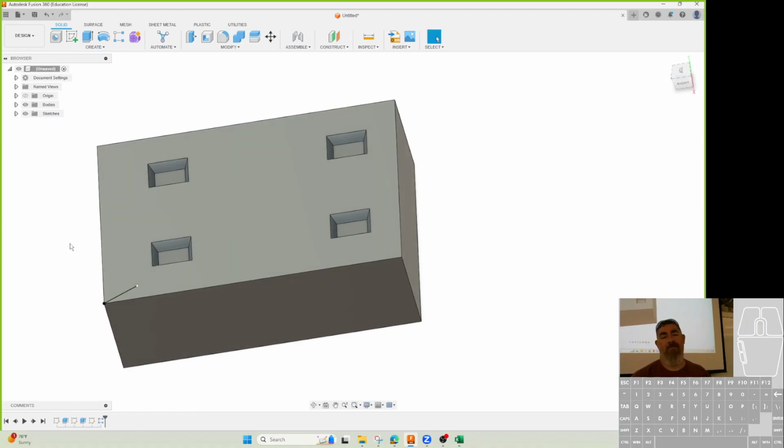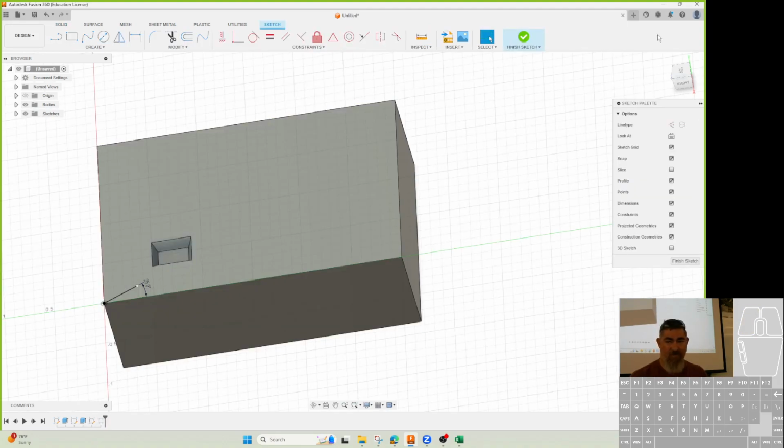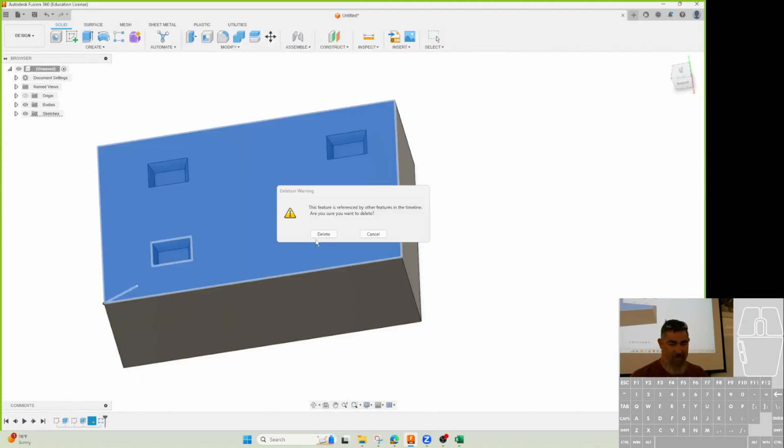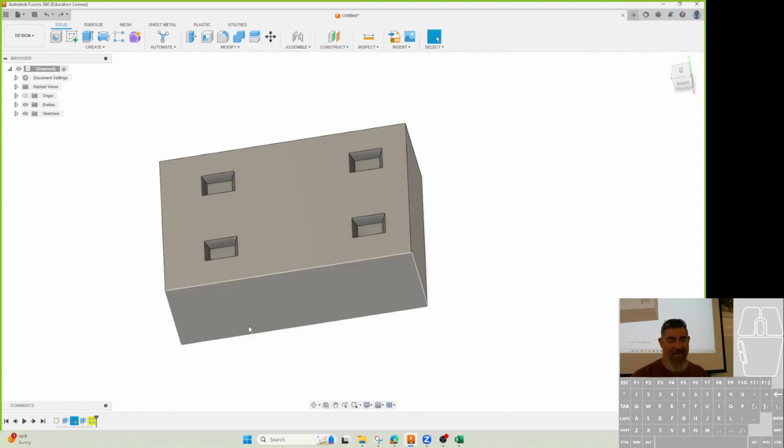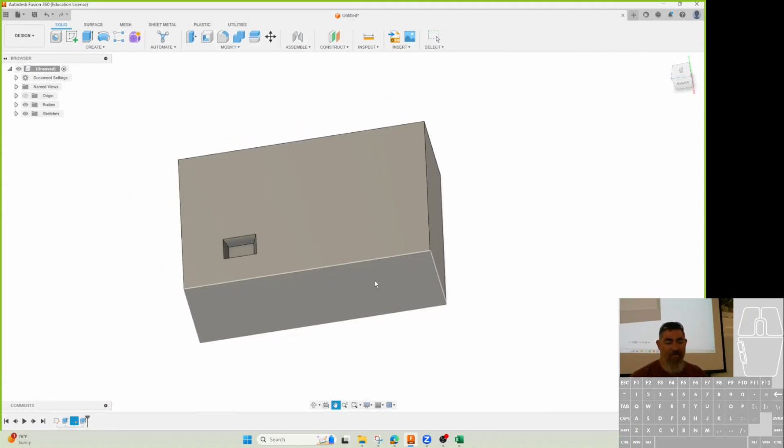So yeah, I was trying to think of a way that you could do that. You could draw the original item on the center of the part. Like if you were to draw that first extruded sketch on the midpoint of the part, then you could pattern with a symmetrical pattern and then just suppress the original. But I'm not going to be able to give it the distance from the edge to the thing without using an equation. Oh, yeah, okay. I'm an algebra person, I don't mind using equations, but yeah, I get you. Yeah, so that's just one of the things to watch out for. So usually for stuff like that, I won't use the pattern.